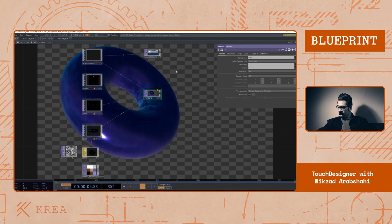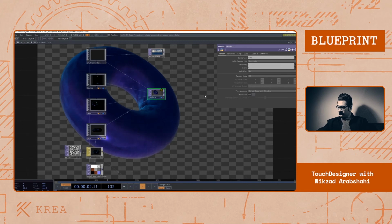And finally, our last piece of this small render setup is the render chop. The render chop is used to render out all of these objects in your 3D scene. And as you can see, it needs a camera, light, geo, and material to work. The render chop is able to render multiple cameras, lights, and geo, and you can simply assign all of these components inside of this render page.